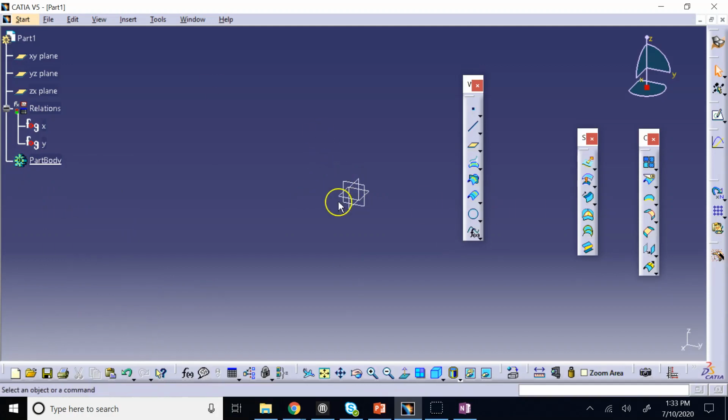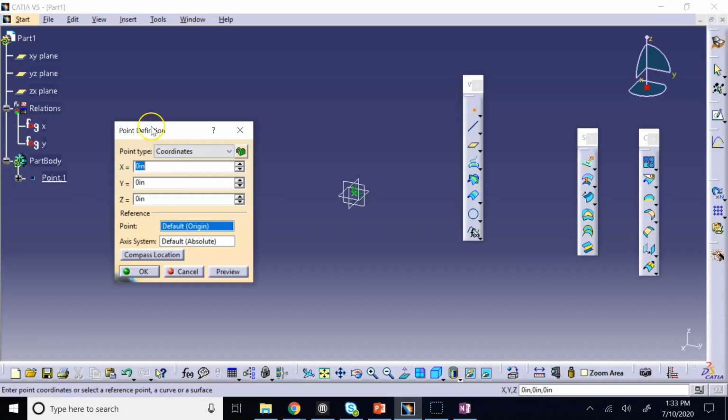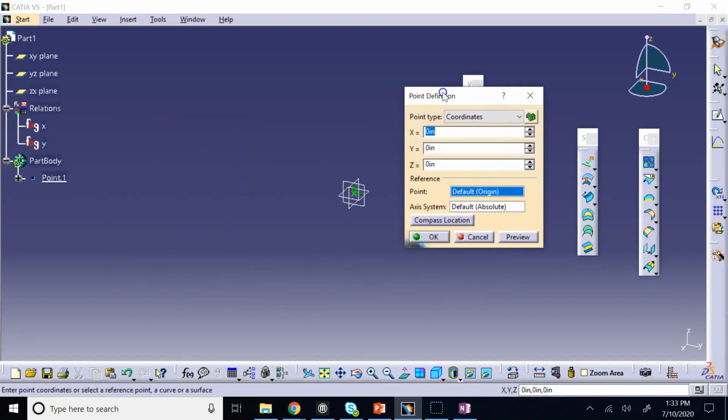So let's say instead of that 2D point command, I use the 3D point command. Just to force it to be on the XY plane, or let's say here, I want this guy, which is YZ plane, I force all of my X's to be what? 0. Or if I want it on XY plane, I force all of my Z's to be 0. So when I want to calculate X for the first point, I don't type the number, I say what?